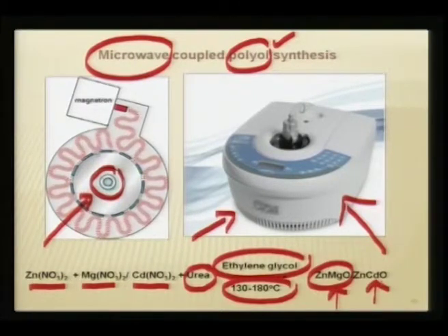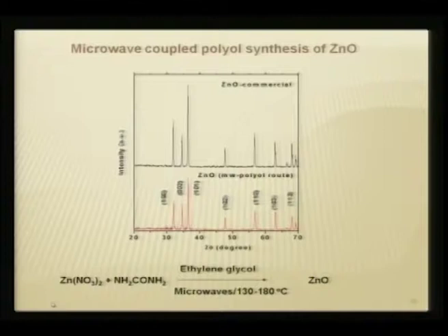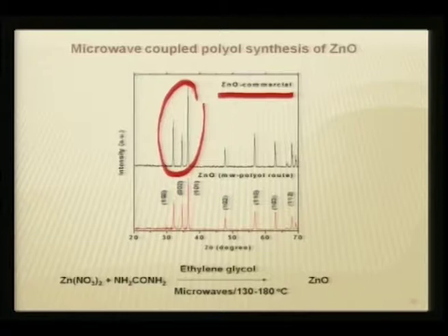In this lecture I will specifically try to show you how critical these chemical routes can be in order to hold the photoluminescent properties of these alloyed zinc oxide compounds. Now, this is an XRD cartoon which tells us the X-ray pattern of a commercial zinc oxide, and this commercial zinc oxide shows the hexagonal feature, typical of the 3 peaks that come around 30 degrees.